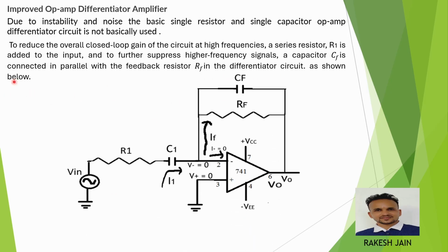So this one is the practical differentiator circuit. Here we have to do one minor change. One parallel capacitor is added in the feedback path and one series resistor is added in the inverting side.